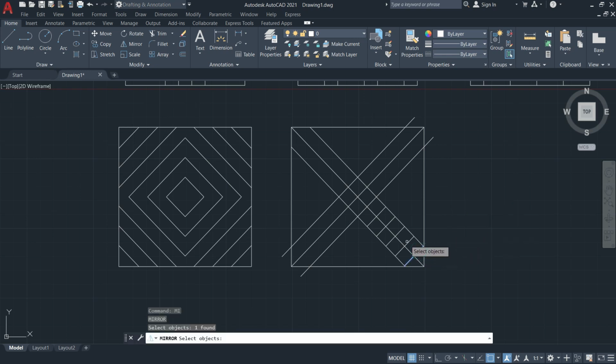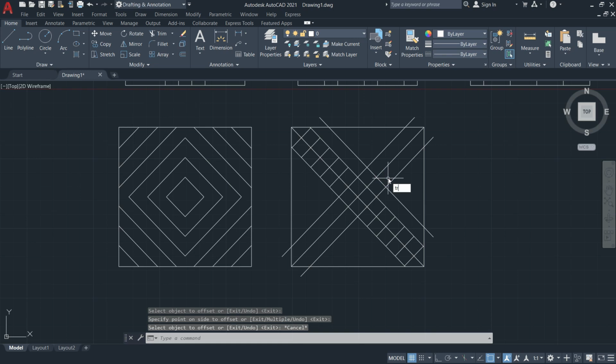Then I'll select these line segments. Okay, and then enter, starting at the middle, connect it to this one, to the corner if you wanted, or up to this point here. Then I'll just click here and then click no. Okay, then similar is applied. I'll just use offset 10. Let's say this one. Then I'll just use trim with cutting edges using these line segments. Then I'll just remove this excess part here.